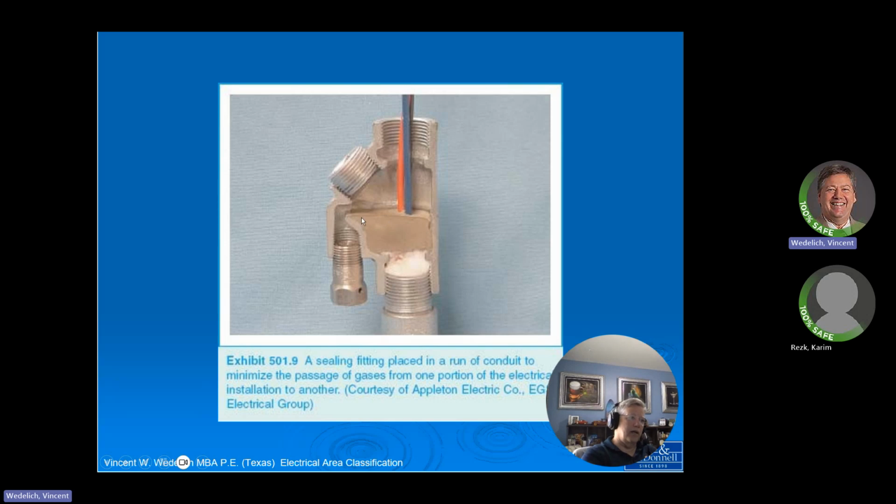So here's another example. This is more like a resin type stuff. They've kind of changed it up a little bit. Still no different. You see from here to here it has to be 5/8 inch. And the number of conductors coming and going has to be less than 40% fill if it's a standard fill. This is a breather drain. So when condensation builds up in here, it should fall this way.